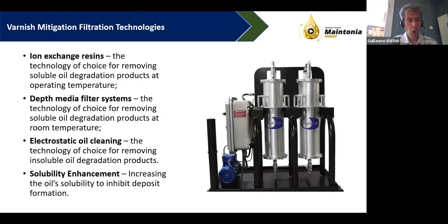So to summarize, we have this ion exchange resin technology, which we call ESP, which works by chemisorption, which eliminates the problem. It eliminates all these soft contaminants, whatever phase they are in your fluid. Then we have depth media filters, which can help with some of the insolubles and very, very fine particles. Then we have electrostatic oil cleaning, which cannot eliminate the problem fully in mineral oil.